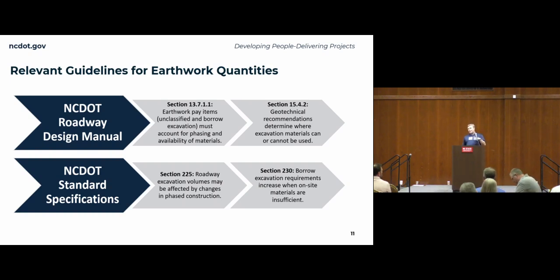In Division 5, we have a lot of what is called Triassic material, which we oftentimes do not allow in the top 3 feet. I know in a lot of geotechnical recommendations, they'll say that certain material cannot be used in the top 3 feet, probably all over the state. So I would recommend that if that information is created on the design side, make sure that it gets incorporated into the earthwork on the construction side, because